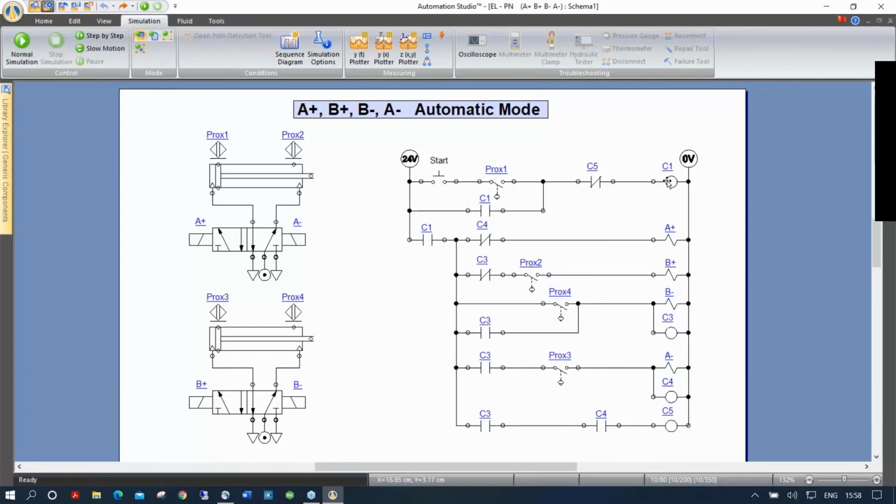You can create a fault in here and they just have to figure out what's wrong. So there are different possibilities like that. I've had people creating circuits where students only troubleshoot. They only open it, run it, it doesn't work. Okay, take a measuring instrument, take the pressure, take the flow. What do you think is wrong? Some will have them do the complete circuit. Some half of it. It's really up to you.